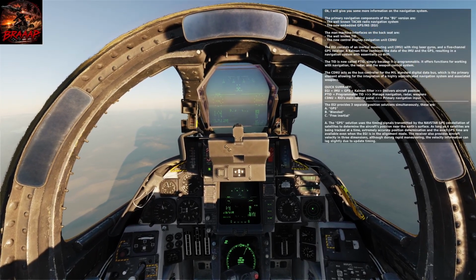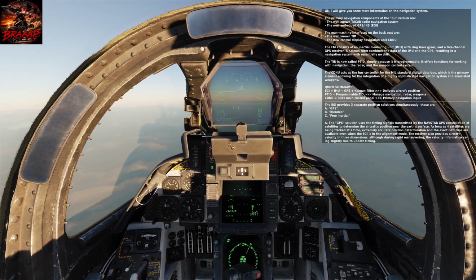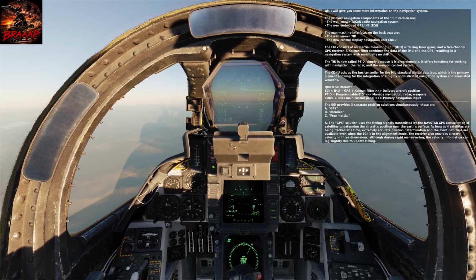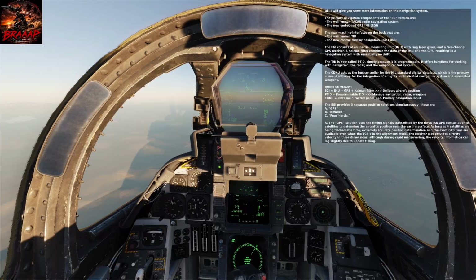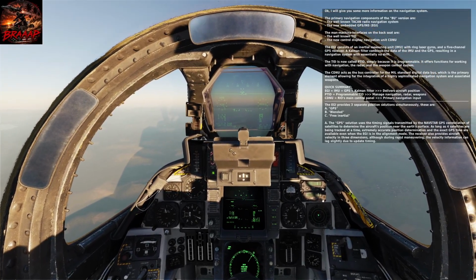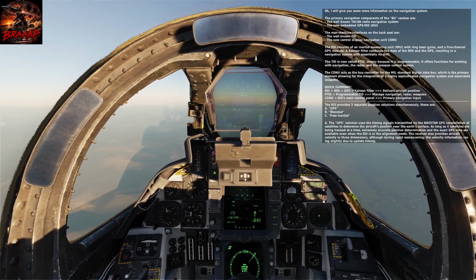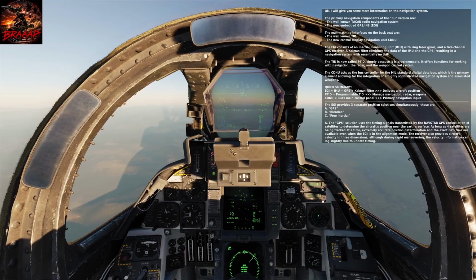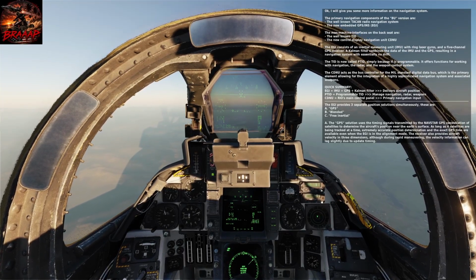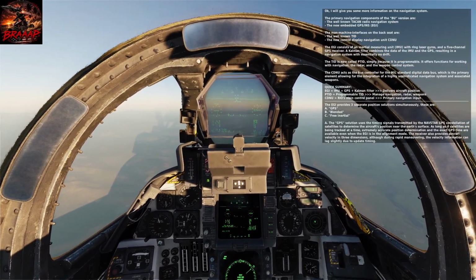The EGI provides 3 separate position solutions simultaneously. These are GPS, blended, and free inertial. The GPS solution uses the timing signals transmitted by the Navstar GPS constellation of satellites to determine the aircraft's position near the Earth's surface. As long as 4 satellites are being tracked at a time, extremely accurate position determination and the exact GPS time are available, even when the EGI is in the alignment mode. The receiver also provides aircraft velocity in 3 dimensions, although during rapid maneuvering, the velocity information can lag slightly due to the update timing.